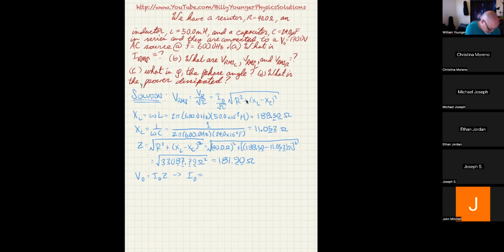Yes. And to calculate V0 from VRMS, we just multiply by the square root of 2. Well, you divide V0 by the square root of 2 to get VRMS. Right. Yeah, so that's in fact where I got the 170 from. I basically took 120, which is roughly what wall voltage is, and multiplied it by the square root of 2, and that gave me 169.7. So yeah, that's exactly right.